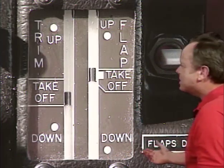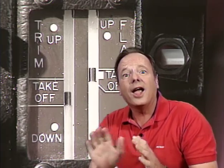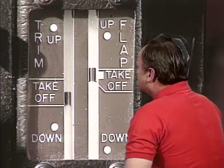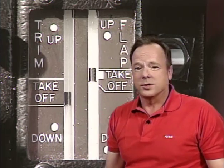Now they ask you a question on a test about the indicating systems for the primary control surfaces of an airplane. In order to be able to answer this question, you have to understand what the primary control surfaces of the airplane are, and they are, of course, aileron, elevator, and rudder. Those are the primary control surfaces of the airplane. So if you have a flap indicating system, which indicates the flap position, does that have anything to do with the primary control surfaces? No, it would not.